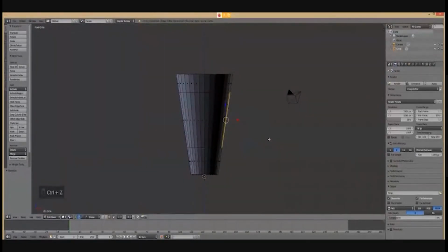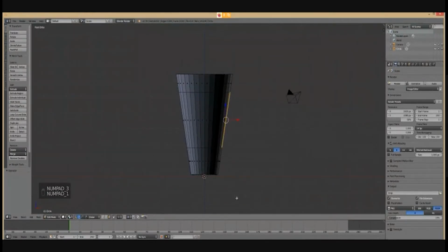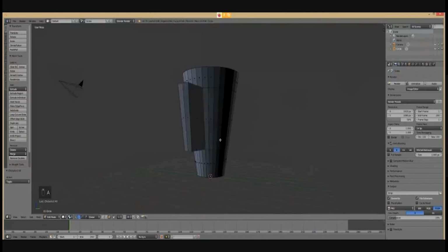The reason why I wanted to select the two faces such that they are in line with one of the axes is because now if I press E and then X, I can extrude it along one of the axes, right? And for that simplicity, I chose the faces along one of the axes. So for example, I can extrude it somewhere. Yeah, that should be fine, right? Okay, so I've extruded it.